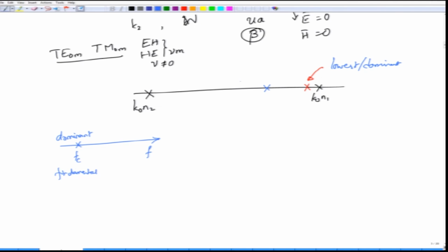Now when you look at the type of modes over here, you might think that the lowest order mode should be the one where m is equal to 0, but unfortunately when you calculate the amplitudes for this case with nu equal to 0 and m equal to 0, the field will not exist. So there will not be any field at this particular mode, and similarly the TM00 mode also does not exist. So you might think, oh well, maybe m equal to 1 can exist, that is, can the TE01 mode and TM01 mode be the fundamental mode?